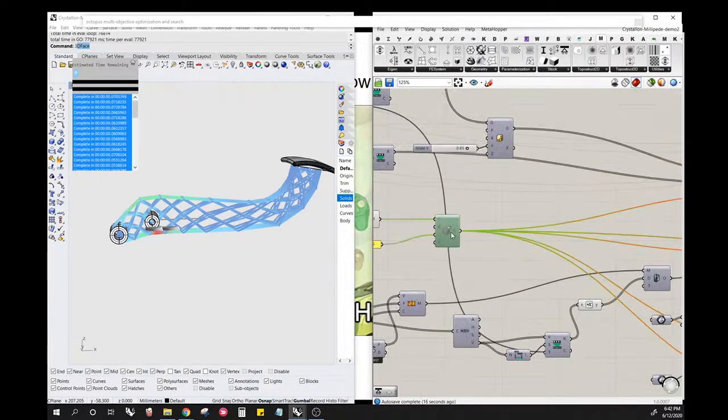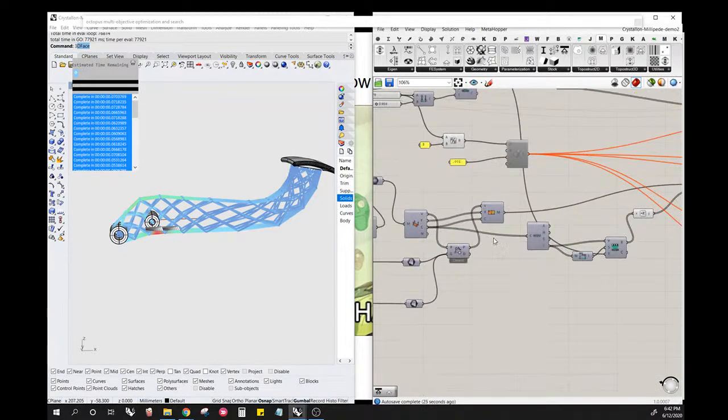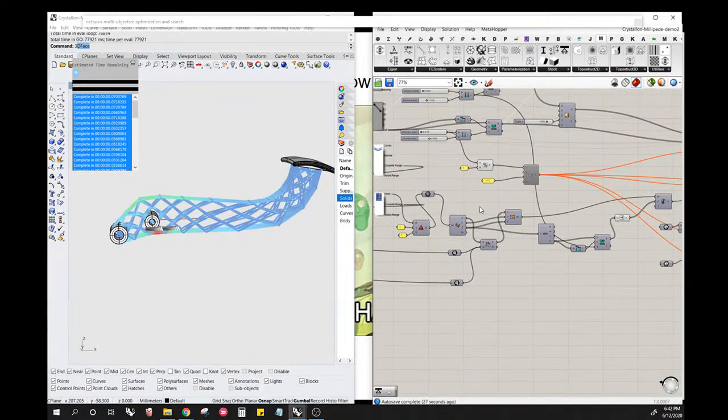And then we use Dendro to create a 3D printable file from these results. And I actually do some modifying of the mesh to make it a bit cleaner. And then what you need to be able to do is validate the results of your final STL mesh, and that's where a lot of software falls behind. Once you create this in topology optimization, it's hard to actually create this mesh model and then simulate that mesh afterwards. So I show you very briefly in the video how it is possible.